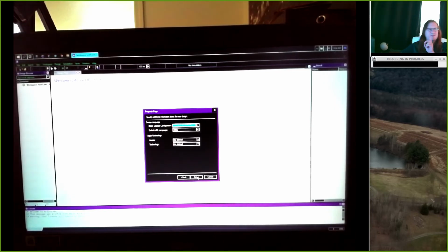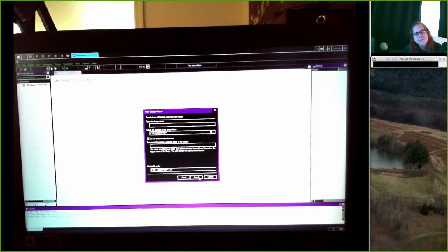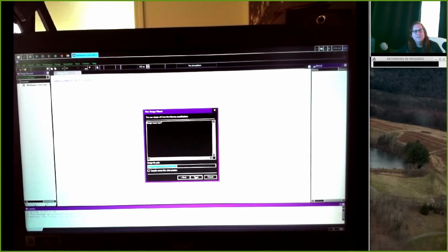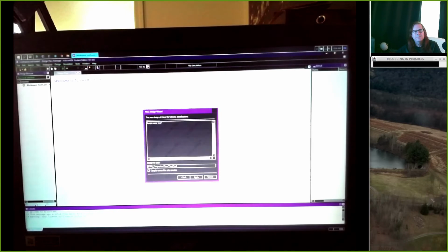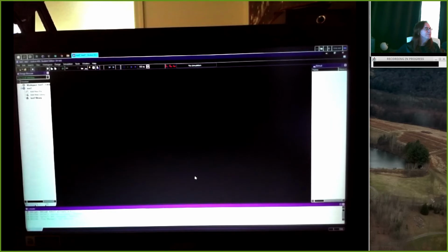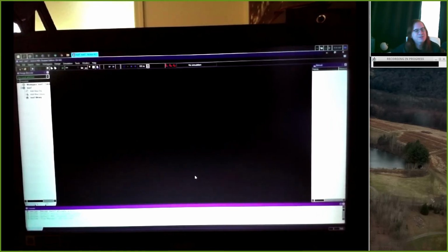And then here's one of the places you have to change the default. This is asking me what language I want to use, and I have two options, VHDL or Verilog. I want to change this to say Verilog. That's important. Then go ahead and say next. Then type the design name. Use the same name you used for your workspace, test 7. Say next. Say finish.